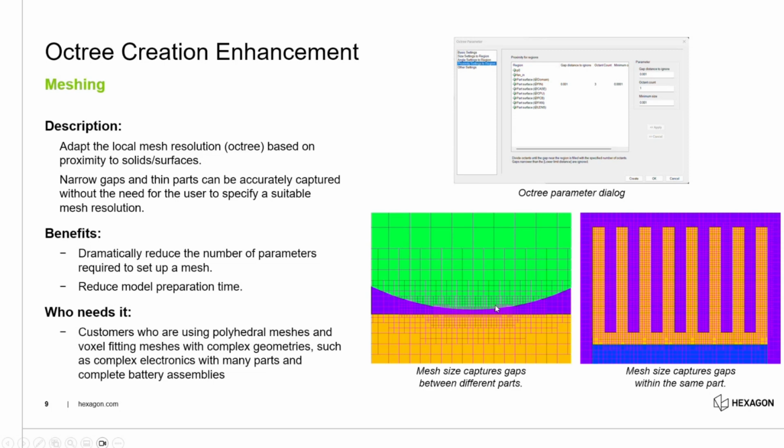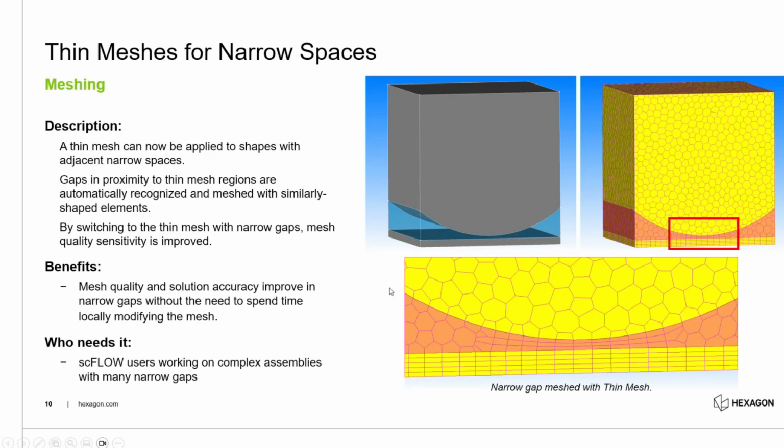There's a second setting related to this, which is not part of the Octree, it's part of the meshing itself. In this case, there's an option that says we still have, and we can see we've got, large elements there, the same size as these, but these are kind of boundary elements that were then extruded all the way up to there, where previously we would have tried to fit those kinds of elements in there with this large setting. So again, this is a great example for that aileron and wing example.